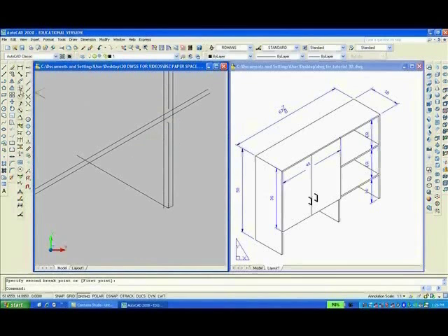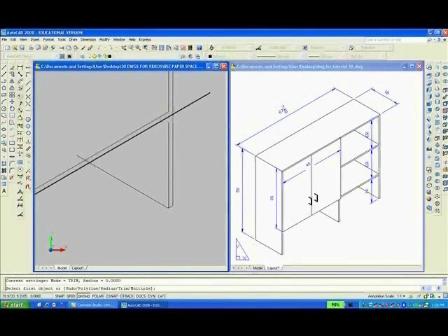Want to erase this line and fillet it, radius 0, here, and trim, TR, enter, from this line, enter, that one, enter.